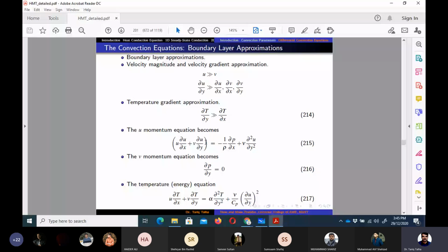As I told you, we can solve these PDEs by using the similarity solution which was given by Blasius. We called it the Blasius solution, in 1907. He converted these PDEs into ODEs by using similarity functions. But that is an analytic way of doing things, and we are more towards the experimental or numerical approach. So that's why we would go to the second route, which is that first of all we need to non-dimensionalize equation 215 and equation 217.